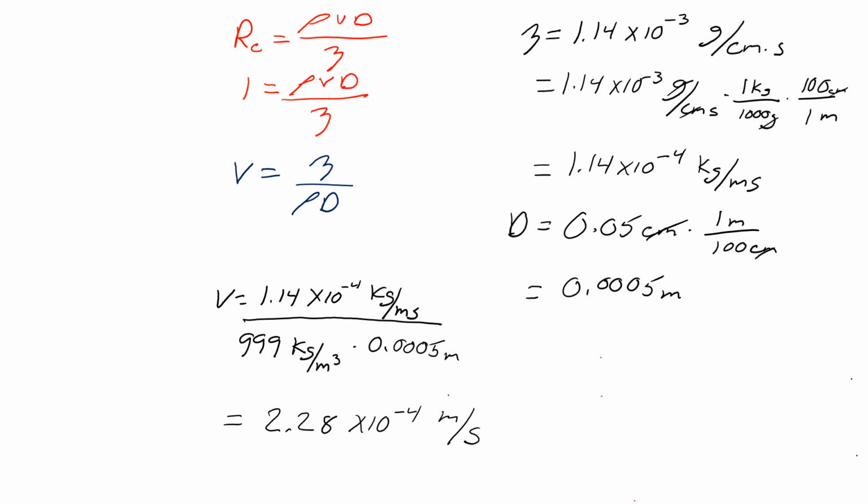So, Darcy's law describes movement through material that has pores. It's only valid if there's laminar flow. The way you determine if something is flowing laminarly is to calculate the Reynolds number. Normally for a stream or some sort of open channel, that doesn't have a bunch of rock and debris in it, your Reynolds number transition between laminar and turbulent is 2,000.